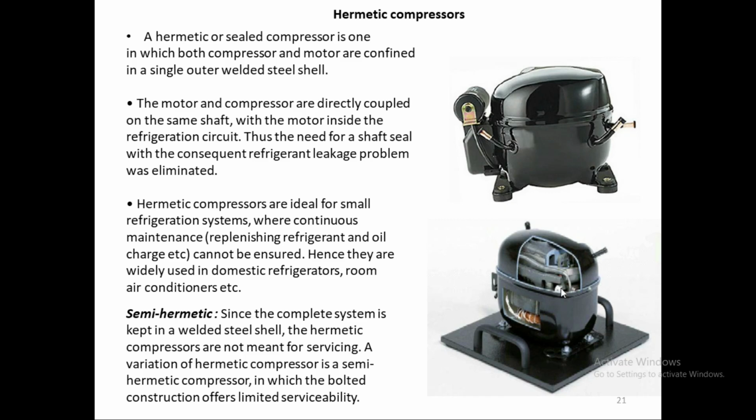Once your compressor has gone bad or your motor has gone bad, you have to throw away your entire compressor and put a new one in there. But to avoid that, we have the semi-hermetic one, where this upper portion is bolted down with the bottom portion, so that it can be repaired. Some repair work can be done on it. So this is the top part and this is the bottom part. Okay. So in the hermetic type, these two are welded, but in the semi-hermetic case, they can be